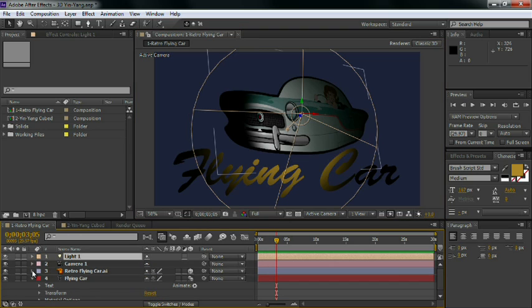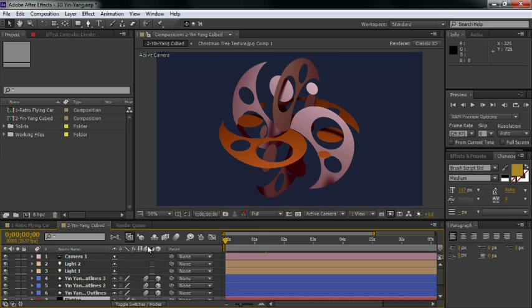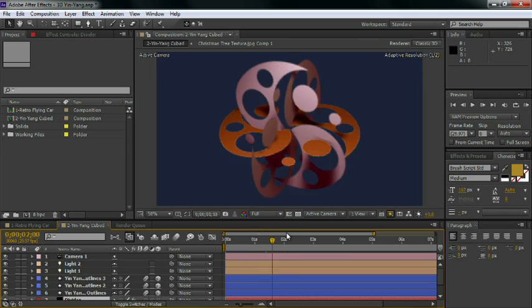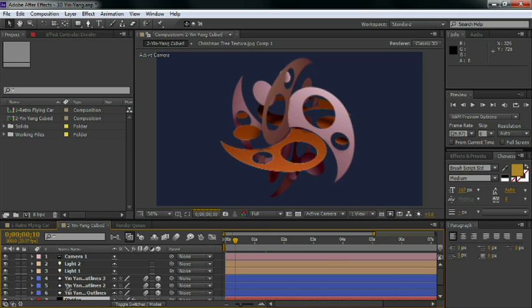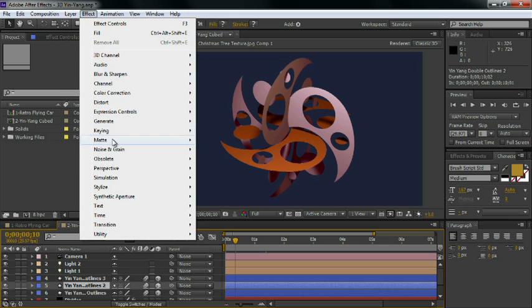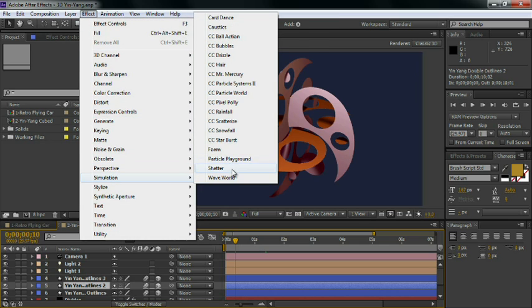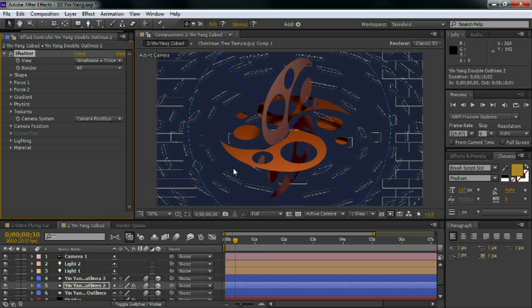There are a few other caveats when working in After Effects' 3D environment, enough that, since its introduction, it's been referred to as 2.5D. That's perhaps a little unfair, especially in light of recent developments, but it helps to know your limits just the same. For example, while 3D layers can interact with each other, casting shadows and intersecting, etc., 3D effects applied to layers, even effects like shatter or card wipe that use the comp's camera coordinates when rendering, cannot interact.